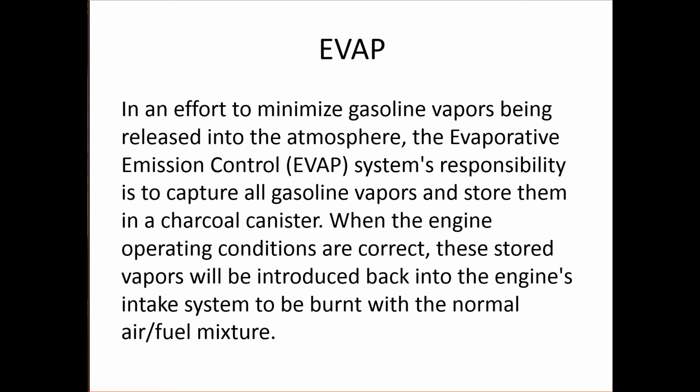So the EVAP, Evaporative Emission Control System, was designed and spec'd out. The goal is to capture all those vapors in a charcoal canister. Then when the engine conditions are right, the system reintroduces those to the intake manifold so that those vapors are actually burnt with the air-fuel mixture. That way the hydrocarbon emissions are reduced tremendously.